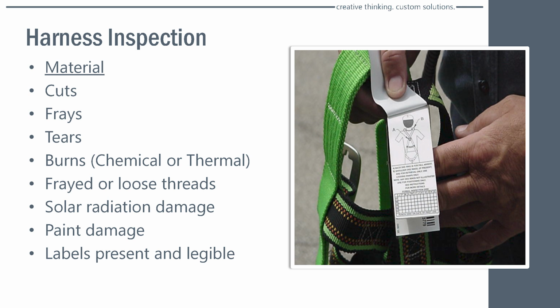How many? That's a problem, because what we get into, we start seeing loose threads. Well, how many loose threads do I have to have before I take it out? I don't know. It depends upon the manufacturer. What do they say? Some manufacturers are different. So if I say you only need 5, somebody else says you need 2, go back and see what the manufacturer says. Okay?